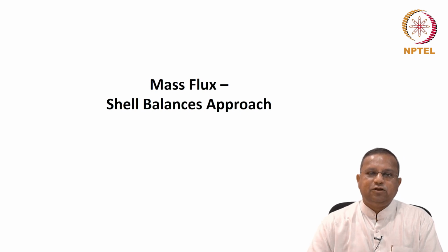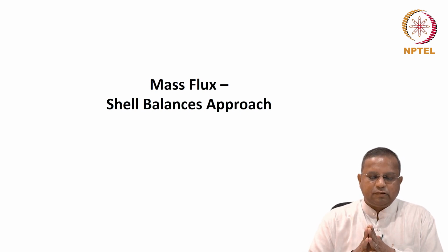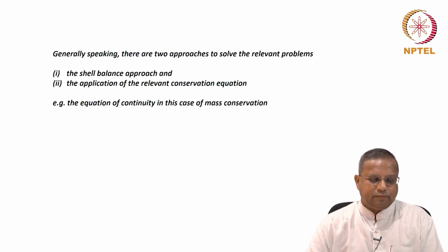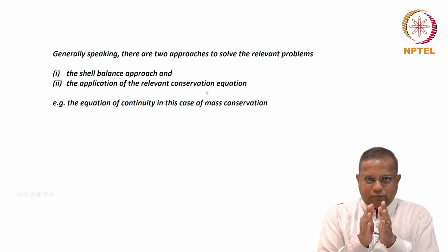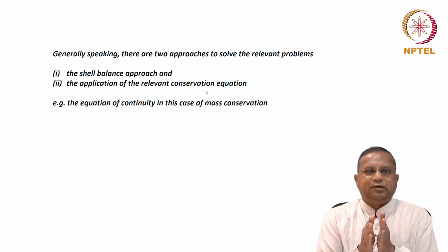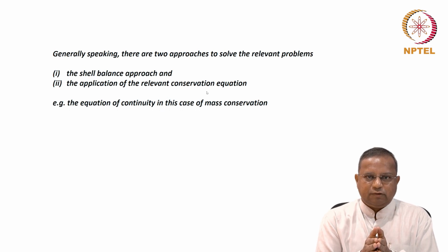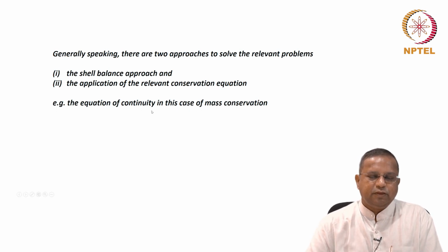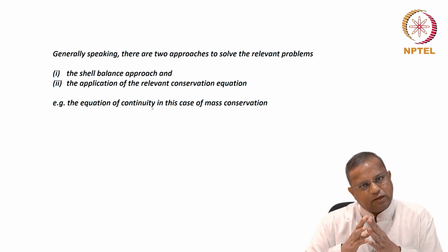We said that you could approach these problems in two different ways. One is a shell balance approach, and the other one is application of the relevant conservation equation. A shell balance approach means that we do a material balance over a thin representative shell. That shell depends on the geometry of the system. If it's a rectangular system, then we use rectangular Cartesian coordinates, a cuboidal system. If it's a cylindrical system, we can use cylindrical coordinates. If it's a spherical system, we can use spherical coordinates.